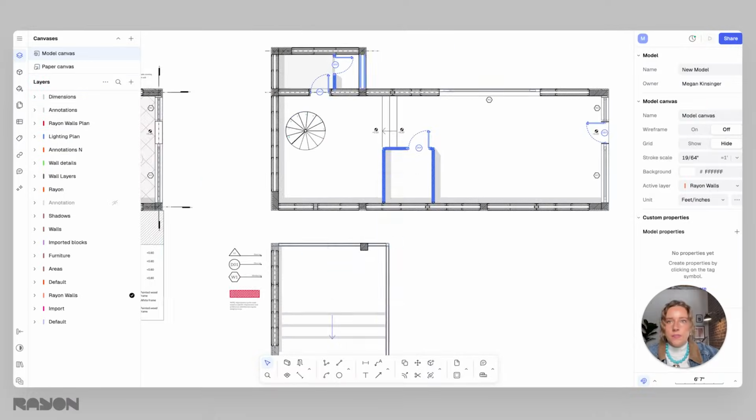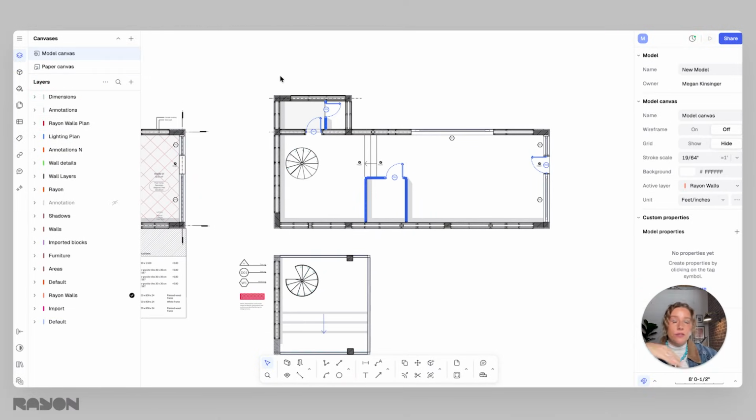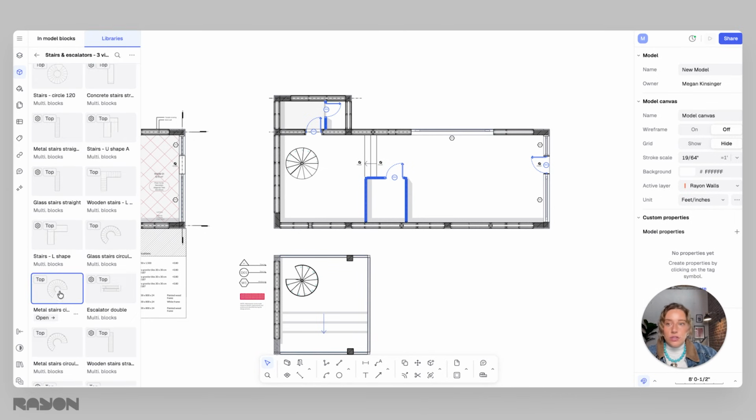In this tutorial, you will learn how to build a smarter, more efficient staircase design workflow by turning your stair drawings into reusable, adaptable design assets. We are going to focus on creating flexible stair templates, building CAD blocks for treads, risers, stringers, handrails, and guardrails, and setting up detail libraries that can be quickly customized so your expertise can compound with every project instead of starting from scratch.